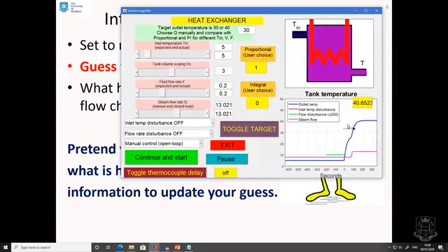Well, you can see the steam flow over here has got to 40. Okay, so we made a guess, and our guess was wrong. So we get the wrong temperature. Now, what happens if we get some disturbances? What's likely to happen is from time to time, the inlet temperature may change. You have no knowledge of this, so look, the inlet temperature's changed.